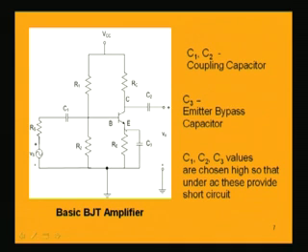If the AC signal is present in this resistance Re, then the voltage gain will be reduced because of this drop, and that can be avoided if we connect a capacitor in parallel to this resistance Re. If this capacitor is chosen properly, having a high value of capacitance, then the reactance offered by this capacitance will be very, very small, as if it is short circuiting for the AC signal, and that is why the AC signal will be passed through this capacitance, and will not go through this Re.